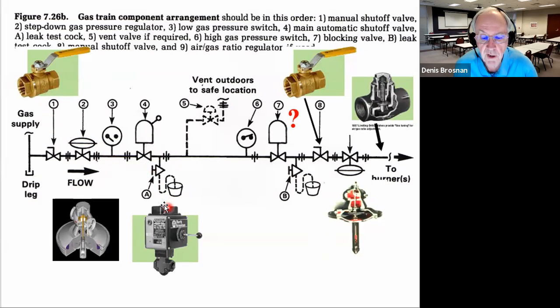And then we have a main shutoff valve, which is basically a solenoid valve. If it loses pressure from one of these pressure sensors, or if it loses electricity, it's going to shut off. You have to go up and manually reset it, and it's in the reset condition right here with the lever down. That means everything's okay, and you don't turn that down until your entire system is ready for you to relight the furnace if that's necessary.